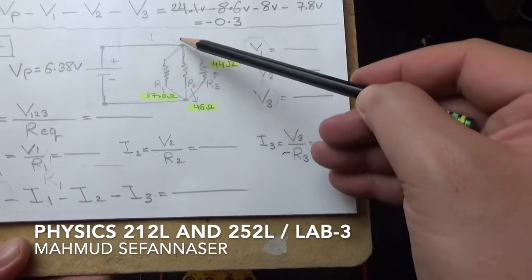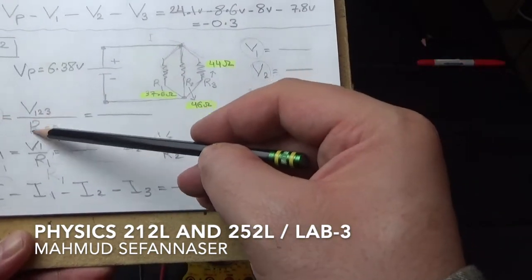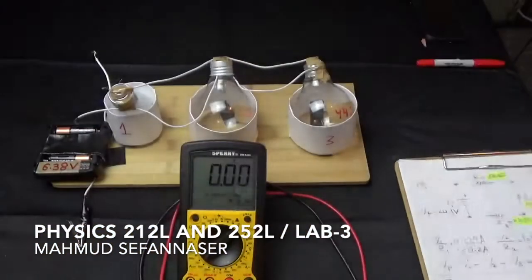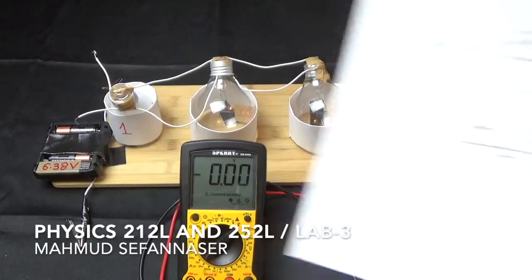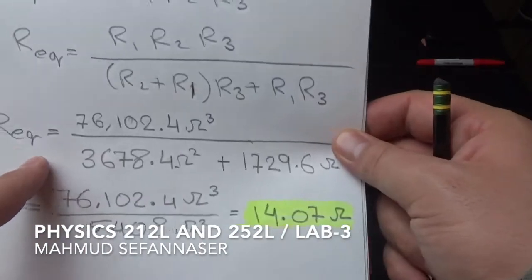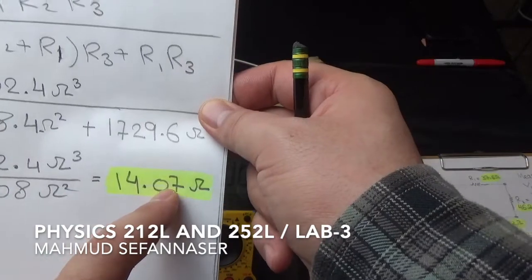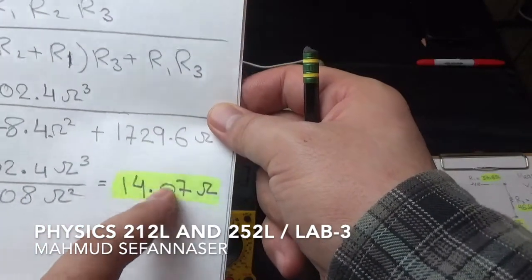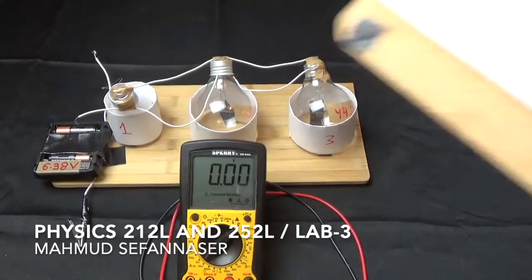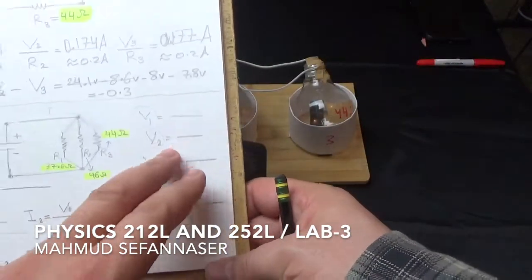Or we can say that it is the voltage across the equivalent resistance. We measured the equivalent resistance last session, and it was 14.07 ohm. So this is the equivalent resistance for these 3 resistors that are connected in parallel. So this is great. So we have everything, guys. The only thing that we are missing is measuring these voltages here. So let's do that, guys, together.